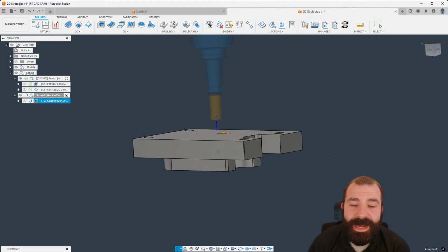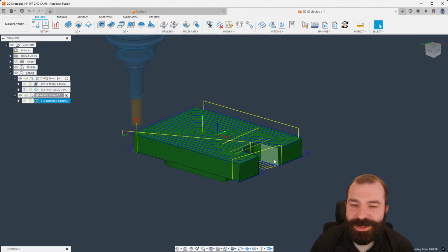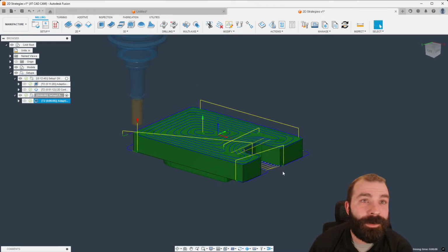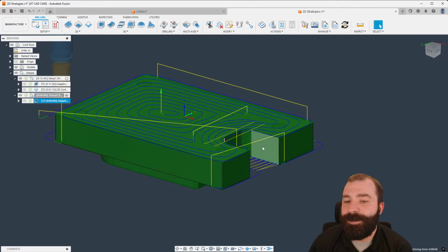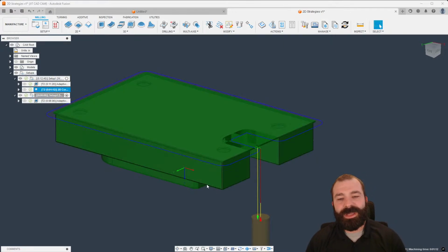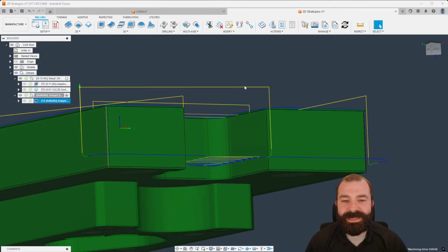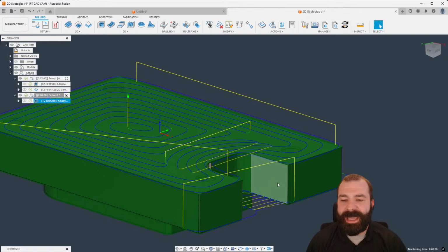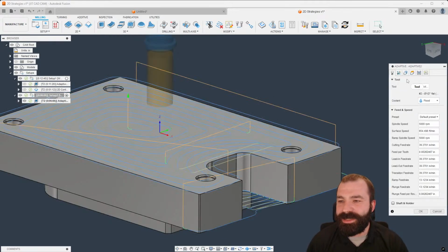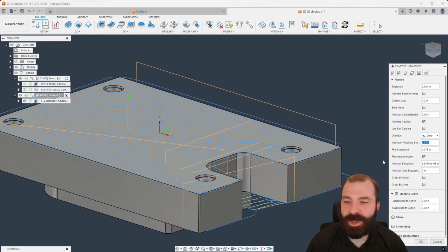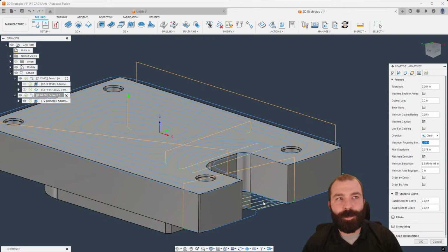But Deep Thinker, you're right for the most part. I would chalk that up to a win in your case that, hey, if we went in and actually finished past that before flipping it, pressed machining should actually work much better, which I believe it is. Now, keep in mind, as you guys can see here, when we think about that tiny piece of material for the hat, what is happening is it's trying to achieve maximum step down first, and then it comes back up, right? If you've ever seen my videos, I've talked about whatever your max roughing step down is, it always goes for that first and then works its way back up.